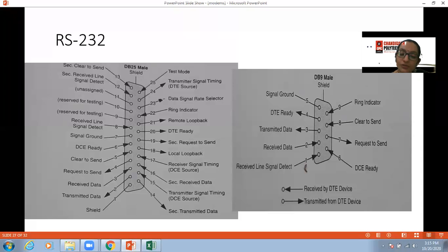Only one serial communication channel with handshaking is present usually, and very few computers have been manufactured where both serial RS-232 channels are implemented. The pinout is also shown, that is a DCE modified modular jack. This type of connector was used on systems built by DEC, that is Digital Equipment Corporation, in the earlier days.